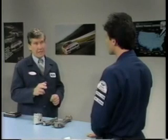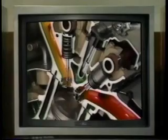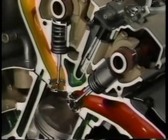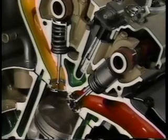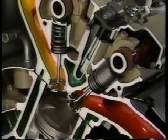In a dual overhead camshaft application, the lubrication happens in a very similar manner. This example shows a V6 dual overhead camshaft engine. Here the oil is fed to each cylinder head through a passageway. Inside each cylinder head, there is an oil gallery which pressure feeds the camshaft journals and lifters. The other components, including the camshaft lobes, are lubricated by spray and dripping oil.